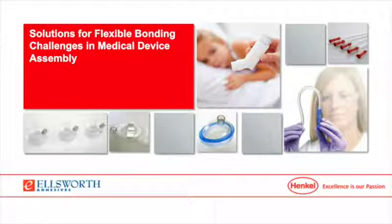There are some other techniques out in the marketplace in terms of adhesive built-in monitors and things like that, but none of those have been as quantifiable and specific as a true analytical test such as IR. So again, typically the recommendation is to look towards a physical test to ensure cure, especially in a production line environment.